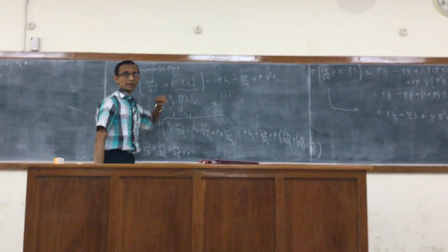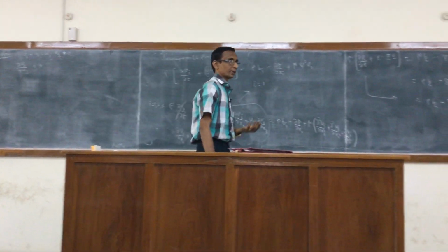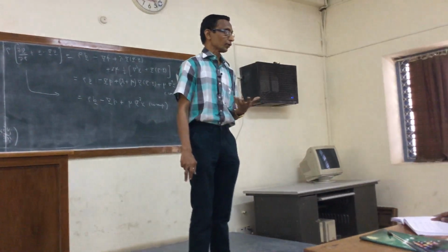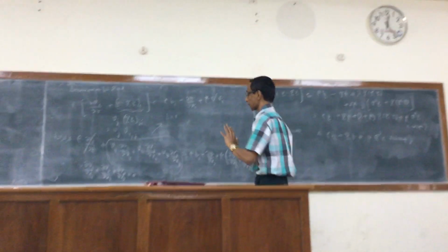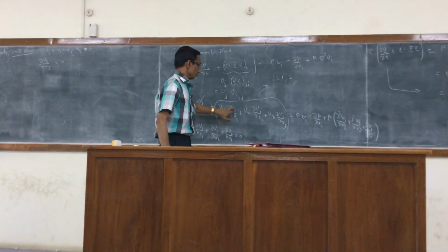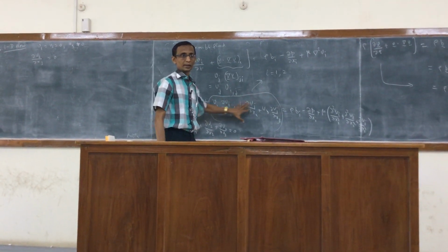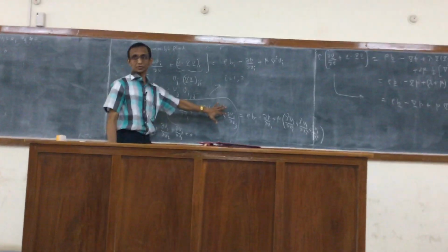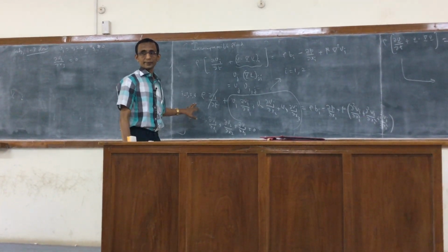But you will find that for one-dimensional flow, where only one of the components of the velocity is non-zero, the inertial terms identically vanish, and you can easily check that because for i equal to 1, 2, V1 and V2 are identically 0, so any derivative involving them will also be 0. So inertial terms would vanish, and with steady flow we are already getting rid of the unsteady term.